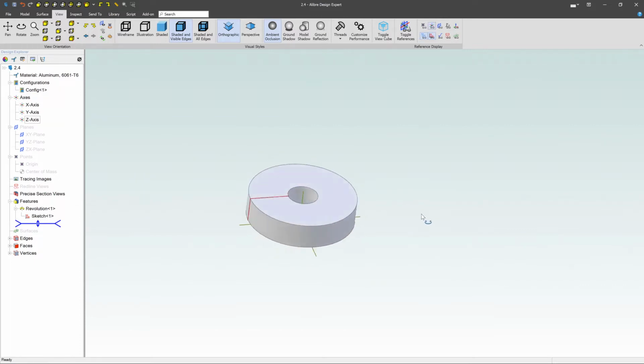Now, of course, I could do a revolve around any axis. It doesn't really matter. I can create my own. I can use the X, the Y, or the Z, your choice, and I can go back and modify that sketch just like I could in an extrude. Anything that I'm putting inside of that sketch will automatically be revolved around. The extrude or the revolve feature are separate from the sketch. They reference each other, but they're independent, right?